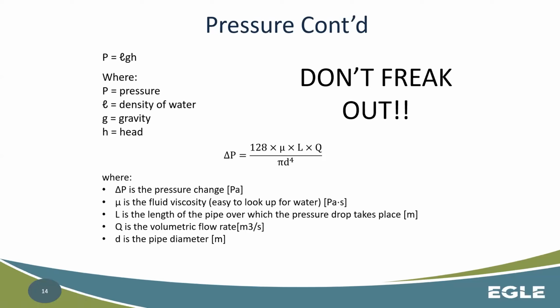So let's first see what happens to area for velocity to increase. If we want to keep the flow rate constant, as velocity increases, what happens to that area? So if area is equal to flow rate divided by velocity, if we increase that velocity, then we're increasing the denominator, right? As we increase the denominator, we are decreasing the area. We have to decrease the area to keep that constant flow rate, right?